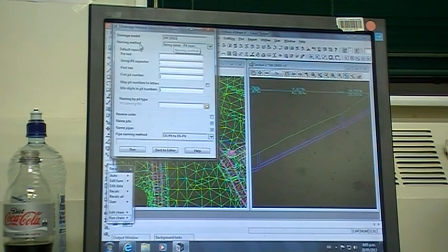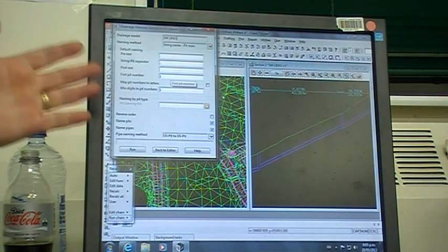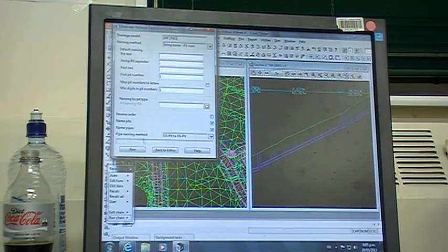It's going to use the string name and then a pit number. So my manhole will be manhole 1.1, 1.2, 1.3 up the line. It's a dot because of that string pit separator. I can put pretext or post text, and it's going to start numbering at 1, etc. Okay, so I'll click run.